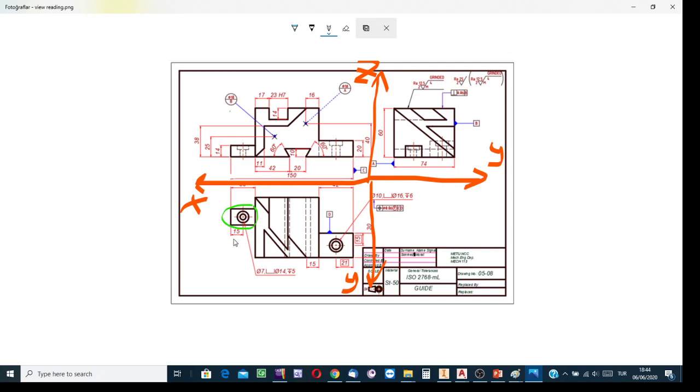After focusing the attention on such a selected feature of the object, see the transfer lines. In doing this, not all of the transfer lines, but I recommend, to save time and effort, the transfer lines passing through the limiting boundaries of the selected feature. Select a different color.